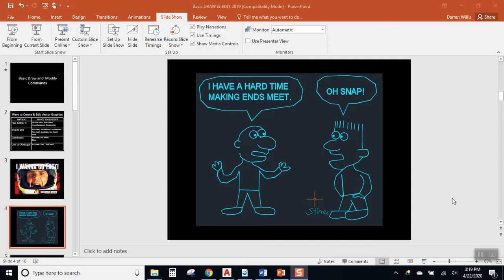All right, so at least for getting started, we've got an ability to go into our drawing and to connect to the things that we've drawn previously without having to worry about coordinates, without having to start and stop every single line on a grid intersection. All right, and that's going to give you some power and some accuracy that we didn't have before. That's going to let you go much quicker when it's time to move and draw and modify things. All right, so the first lesson of the day was using the object snaps or O snaps.